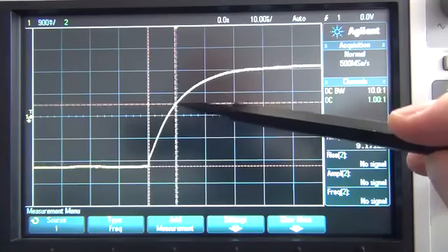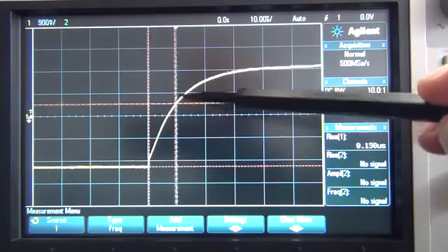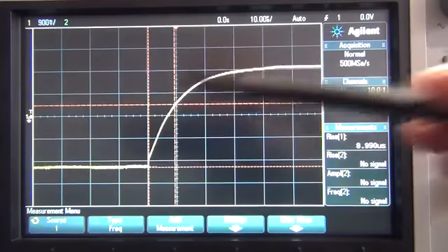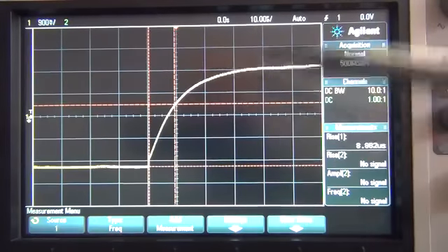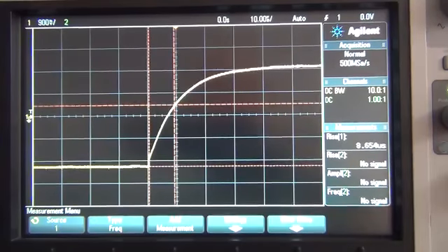Now when I say 63.2, this scope allows me to go to 63%, but the 0.2 for error and the jumping around, the bit of noise I got, is negligible. So we can wipe that out. That's at 63%. And on here you can see it actually gives you a measurement for the rise to that point, and it's bouncing around 8 to 9 microseconds. So again, according to that formula, if that increases, then our capacitance is increasing.